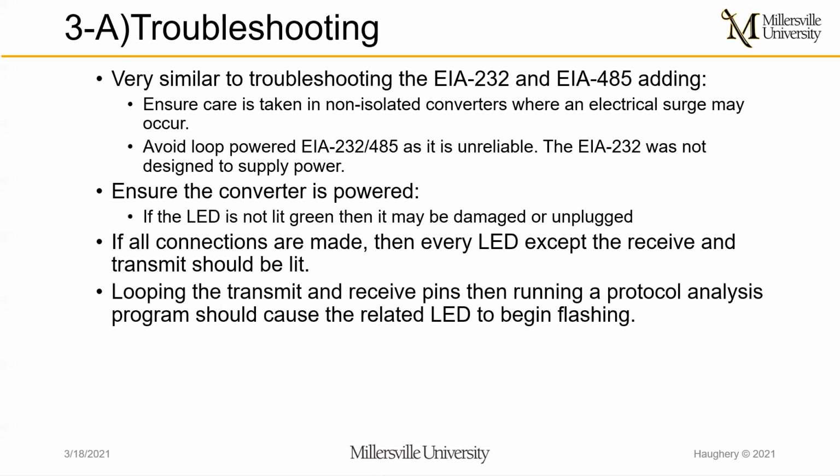For troubleshooting, both are very similar to troubleshooting the EIA-232 device as well as the EIA-485, with the exception of making sure to take extra care in a non-isolated converter where electrical surges may occur. Also, avoid loop-powered EIA-232 to 485 as it is unreliable. As I said, the EIA-232 was not designed to supply power to devices.